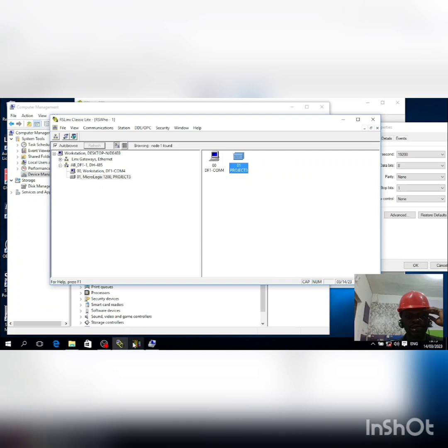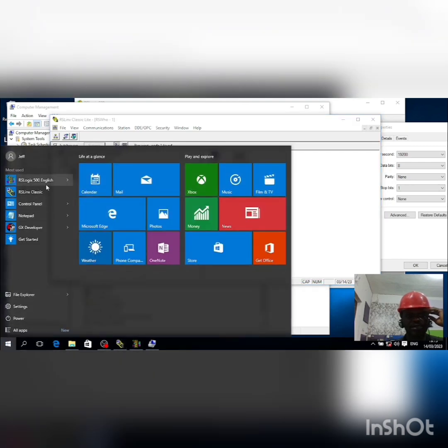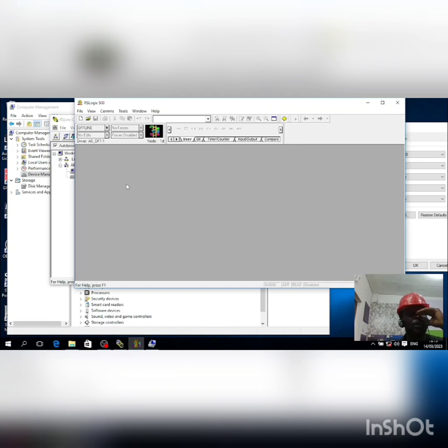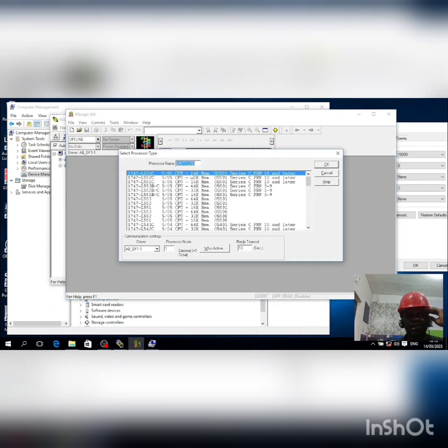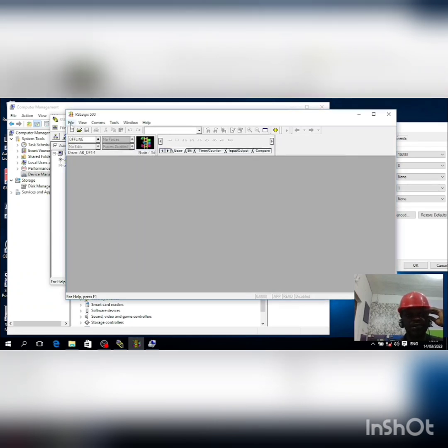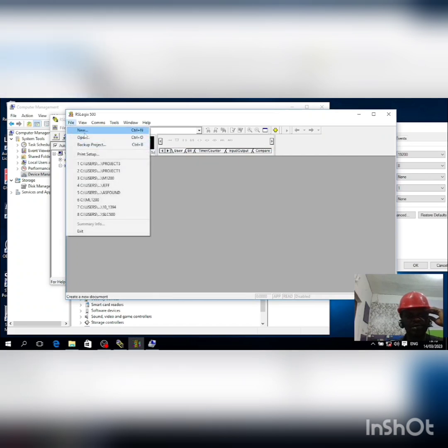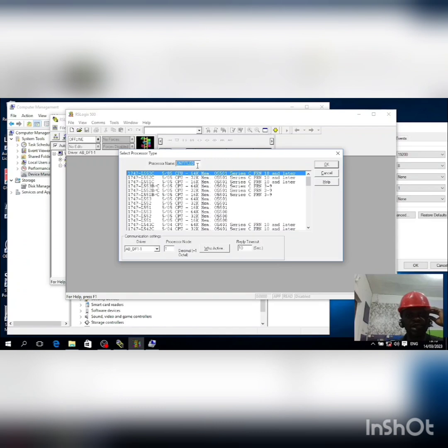Okay. So now you click your RSLogix 500 and open up RSLogix 500. So I want to create a new project. So I want to show you how to create a new project. To create a new project, you click on new here. All right, let me cancel this. Or you can click on file. When you click on file, you look for new. Click on new. It's all the same thing. So I want to name a processor name or project name. Okay, so I want to call it training 1. Okay, training 1.